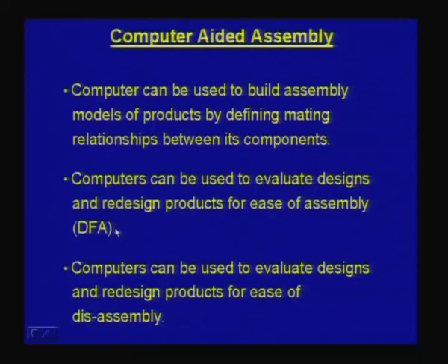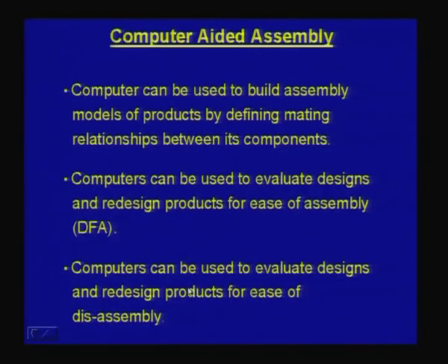And the concept of DFA is not necessarily restricted purely to assembly. It goes one step beyond, where one looks at how easy or difficult it is to dismantle a product, or what we call disassembly. As a part of disassembly, when I am designing a particular product, my concentration would be on how easy or difficult it is to dismantle the product.